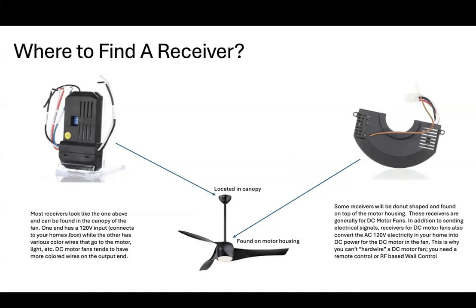Replacing a receiver is easy, however, it is recommended to use a licensed electrician or qualified handyman. Replacement involves disconnecting and then reconnecting the light-colored wires on the fan and receiver. Some DC motor receivers even have quick connects or Molex connectors, so it's even easier.